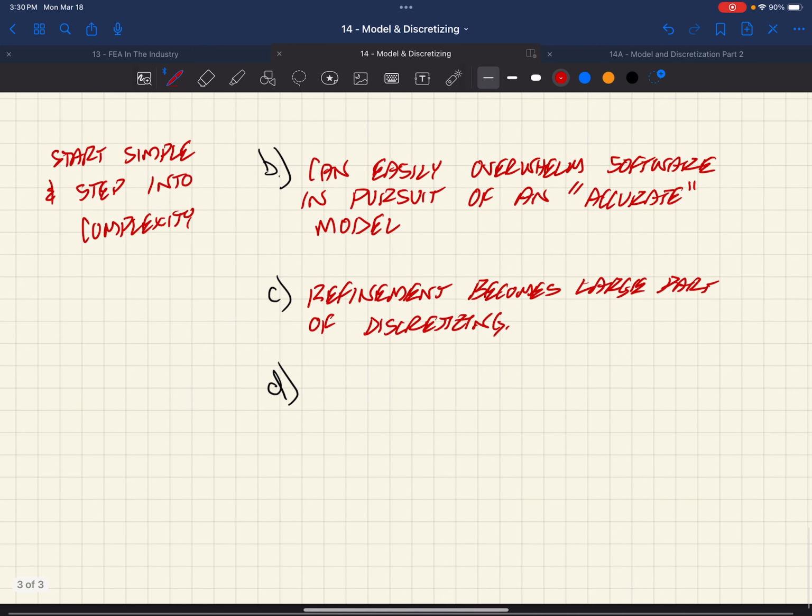You don't have to have the same mesh count for every plate within your entire building, right? In Norm, for instance, there are some areas of that building which are kind of out in the middle, and we're not too worried about what's going on out there relative to force transfer. So maybe we can handle a coarser mesh out there. Maybe our plates are 10 square feet. But then as we get closer to these moment frames, maybe we get down to half a square foot, where we interface between vertical lateral resisting elements and horizontal lateral resisting elements, so our shear walls or moment frames to our diaphragms, our roof elements, right?